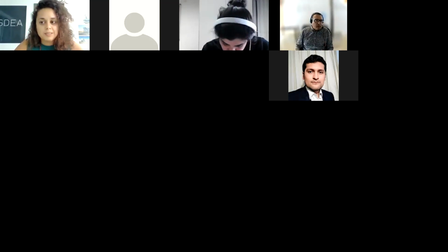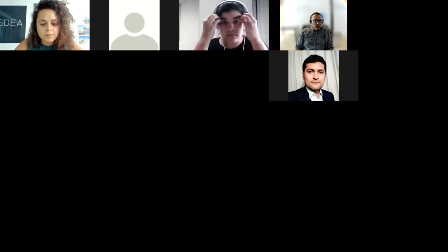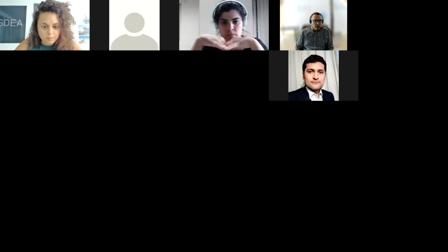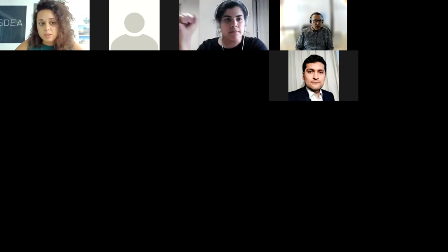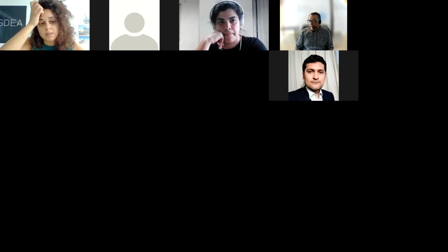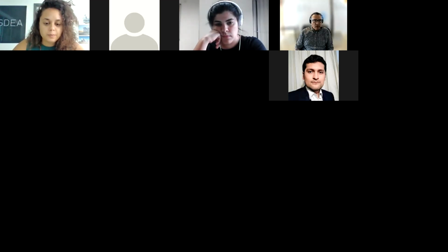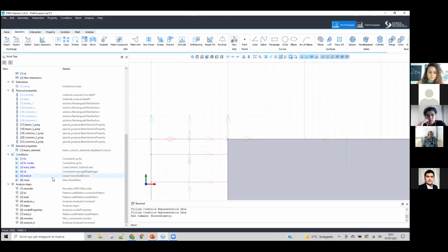Much better. Yeah. So hello, I have a question. First, to clarify a concept for me. Besides adding self-weight in order to perform a gravity analysis, it is needed to add mass on each node to perform the modal eigenvalue analysis, right? Yes. But you can also apply face mass or edge mass or solid mass if you don't want to compute the nodal mass. So my second question is, is it an option to add masses with a certain shape, like a function? For instance, in my modeling, I have to add filling of bolts, so it has a certain distribution, so I wanted to know how to add it automatically.